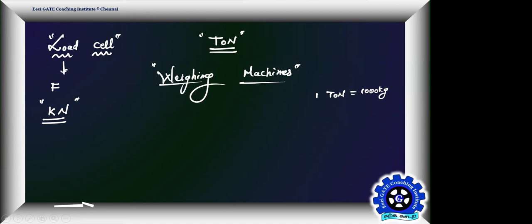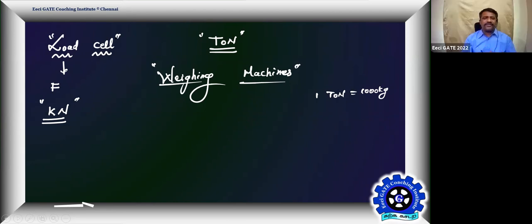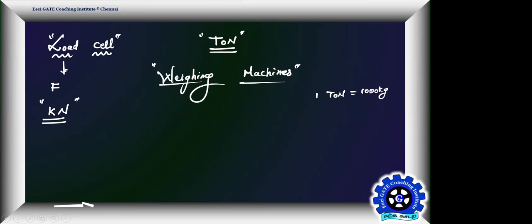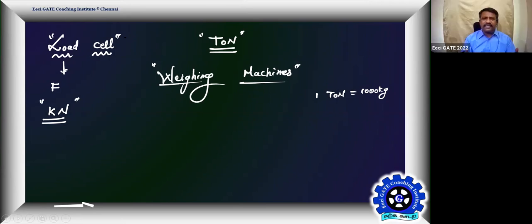So any weighing scale or any weighing machine will definitely have the load cell and use the strain gauge. Then a lot of transduction and signal conditioning is happening inside weighing machines. The output may be a digital readout. Now we see only digital readout in weighing machines, no analog readout. That's a good example of a load cell. We are familiar with them, we are seeing them, but we are not connecting. That's a fundamental. That's a primary sensing element, and we are talking about that only.